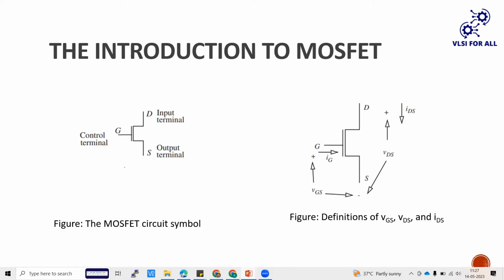Whereas if you take FET or MOSFET, their source and drain regions are equally doped. That means source and drain regions have the same doping concentration, so you can use the source as drain and the drain as source. Hence, FET or MOSFET is a symmetrical device.